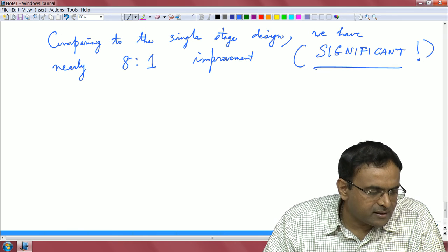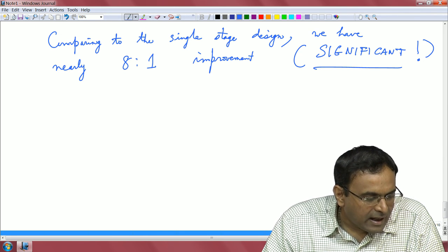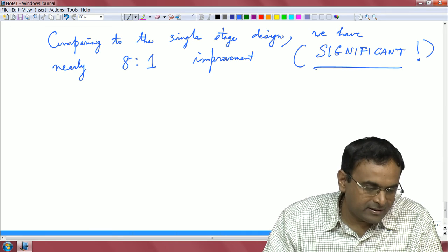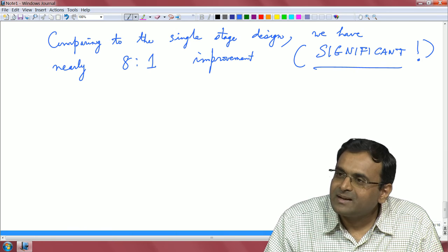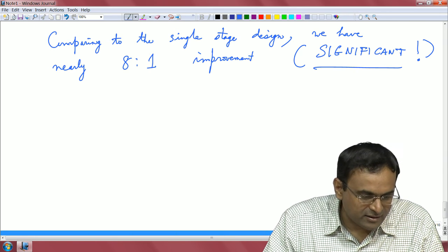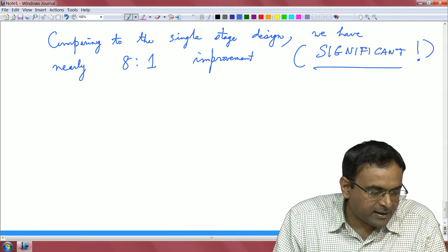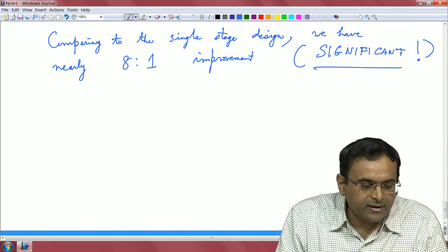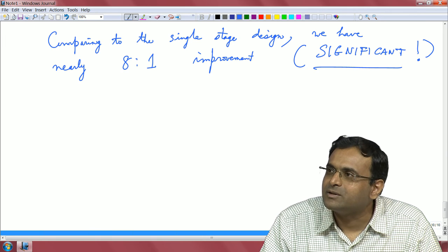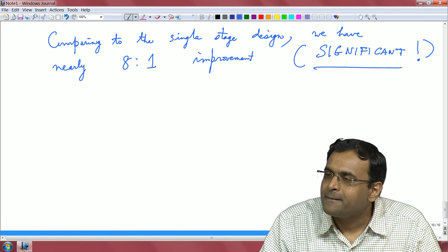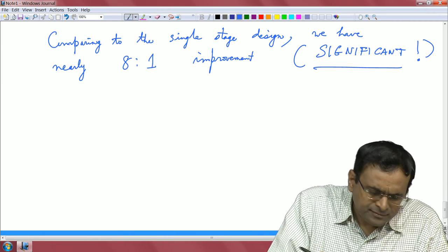And one can imagine that in the early stages the sampling rates are high, and equivalently the transition widths are also large, leading to smaller values of the filter length, and in the last stage the sampling rate and transition widths tend to be smaller, giving lower orders, but possibly comparable to the earlier stages. Okay. So, this is something which you have to note.